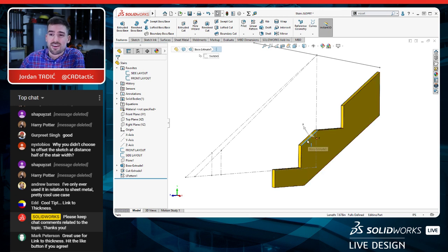I might fillet this edge. I might reverse the extrude direction, and that edge might jump to another edge or something like that. So whenever possible, that's another benefit of creating layout sketches. Make all your references back to that, because you know that's never going to change. If I delete that line in my layout sketch, then shame on me, right? So let's go ahead here.